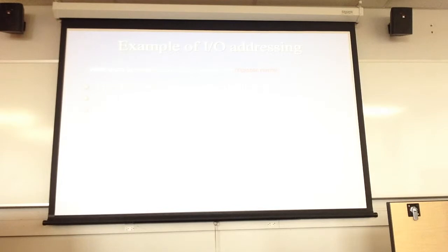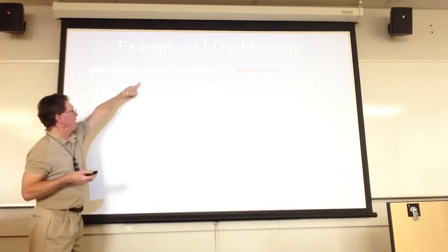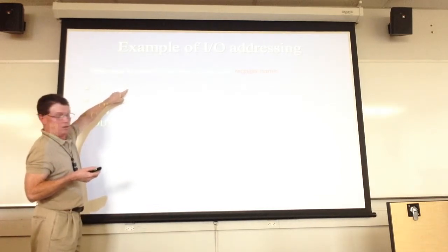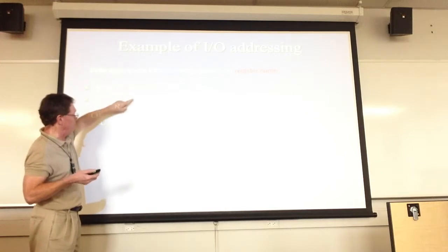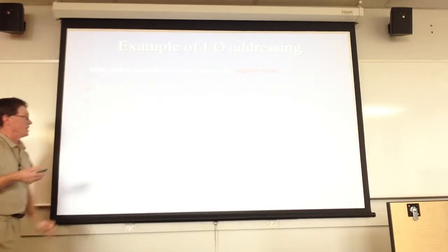All right, so we're going to take 55, send it to port B, and include the register name. So here we're going to load up R20 with all ones, because we're then going to force the data direction register to be all ones, so it's an output. The data direction register is set up.